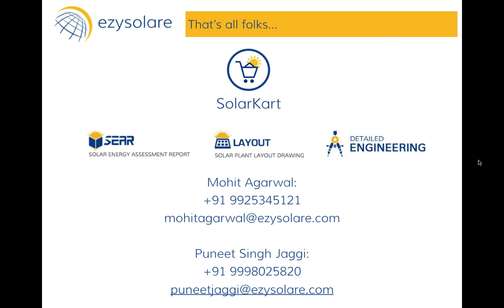Sanya Datta. Now, the typical process of commissioning of a solar power plant is that there are a series of tests which are to be conducted, which is given in the installation manual of individual equipment. So the inverter supplier, the service engineers will come on the ground, they'll conduct those series of tests. The transformer supplier, again, the service engineer would come on the ground and they'll conduct their tests.